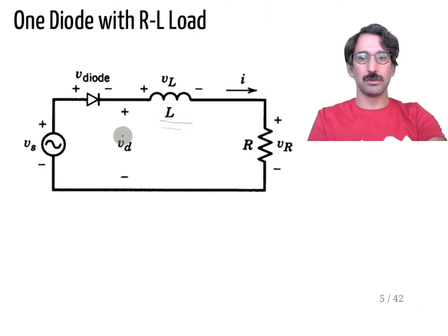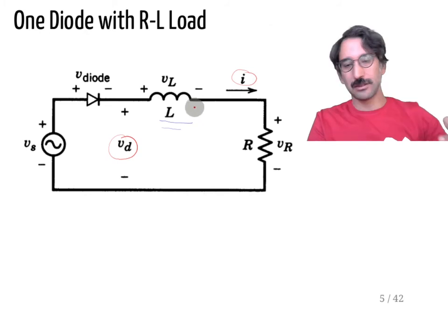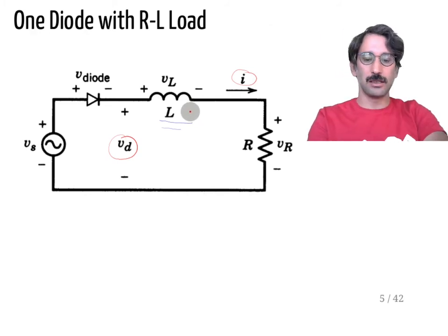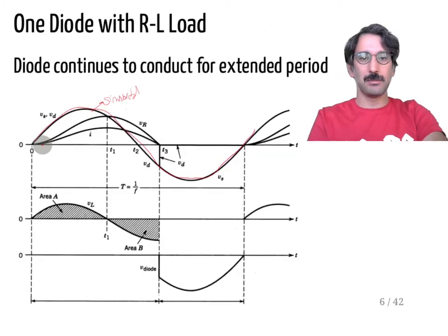So that voltage will not be in phase with the current, and if you think of the inductor, it will take some time to increase the current. Because of that, the current doesn't increase immediately and it's not in phase, but as you can see there is some kind of lag. When the voltage reaches maximum, the current hasn't reached maximum yet, and it actually is delayed, and we will talk about those things.